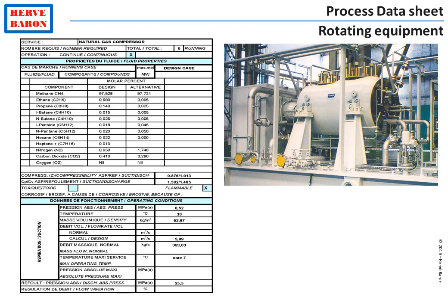For a heat exchanger, for instance, it will include the fouling factor of the fluid as well as the allowable pressure drop. For a pump, it will include the available NPSH. For a heater, it will include the enthalpy curve of the fluid.